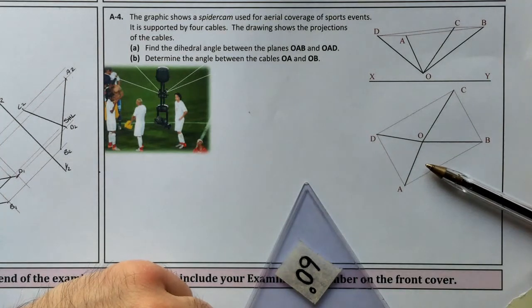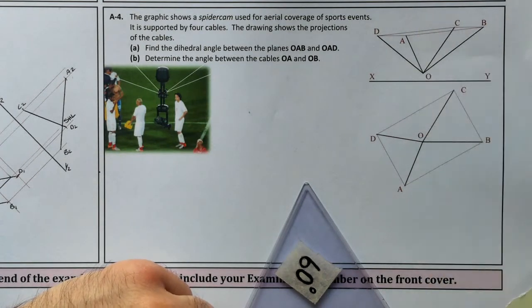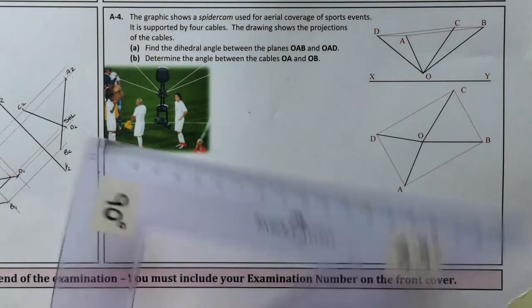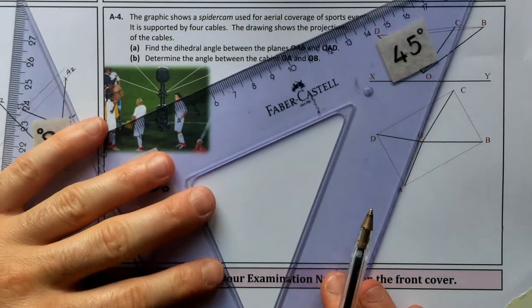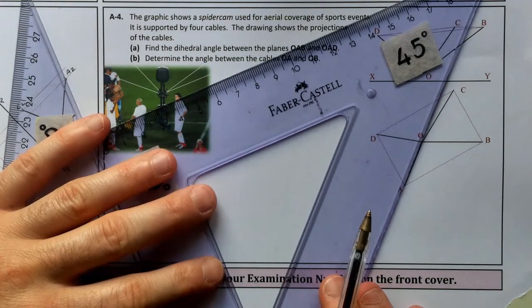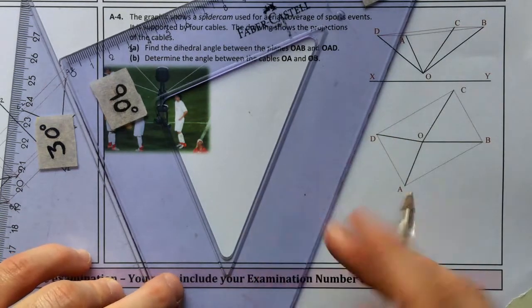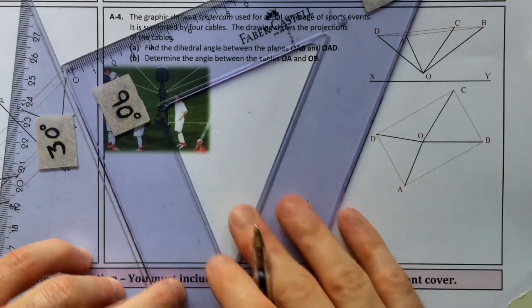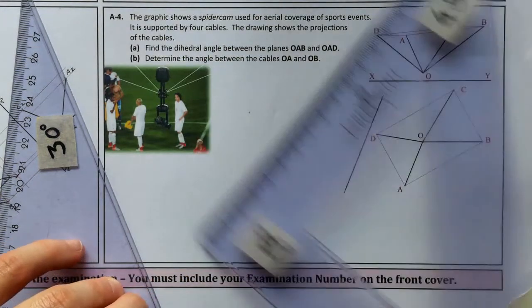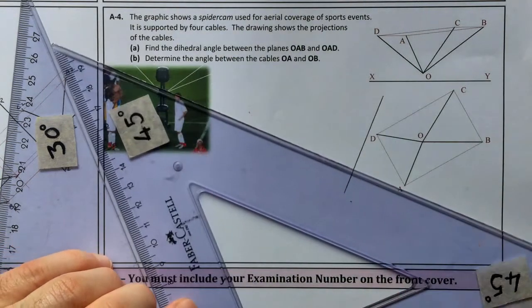If we look at it perpendicular in our elevation, then in our plan we take our heights from our elevation. So, a little bit of sliding sets for us here. We're going to set up an x1, y1 parallel to OA in my plan view. Slide that up like that, and I'm going to keep it close enough because obviously you're working within your space here. And having set that up, just make sure it didn't slip there. Yep. I'm going to project out perpendicular to it.